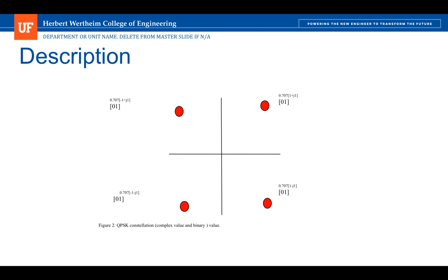For this project, I developed a 64 channel, 64-point IFFT FFT QPSK system, which is shown in this figure. And I used Matlab studies to test my proposed solution. Using Matlab's additive white Gaussian noise, I created a 2 to the power of 6 multiplied by 2 to the power of 6 matrix of noise added random QPSK symbols.